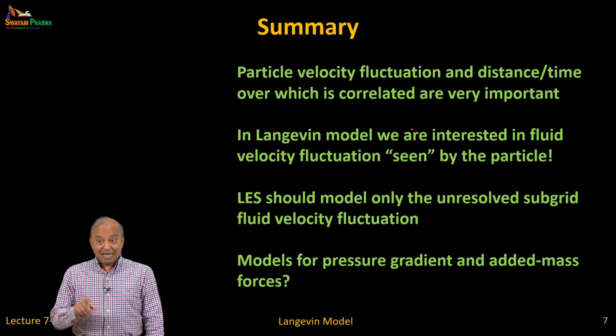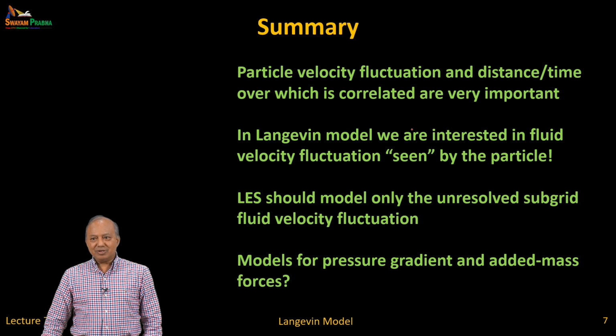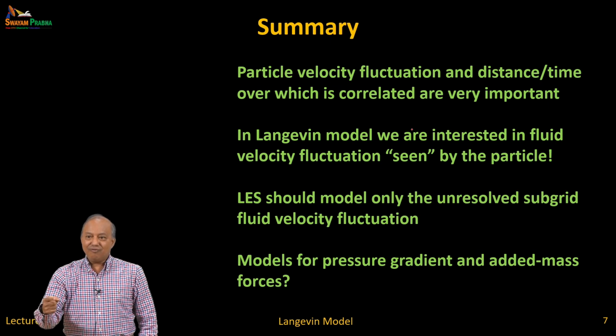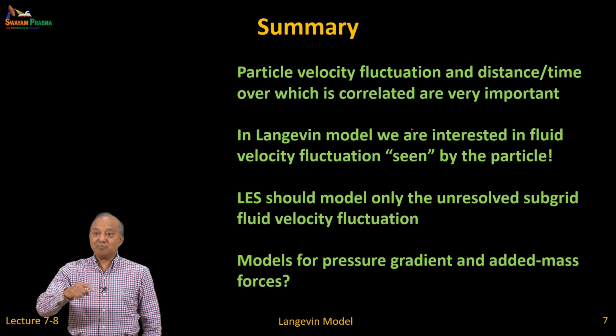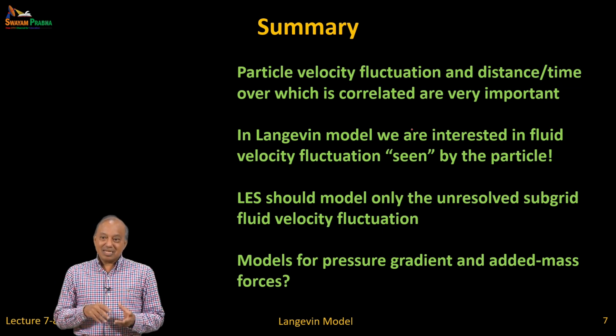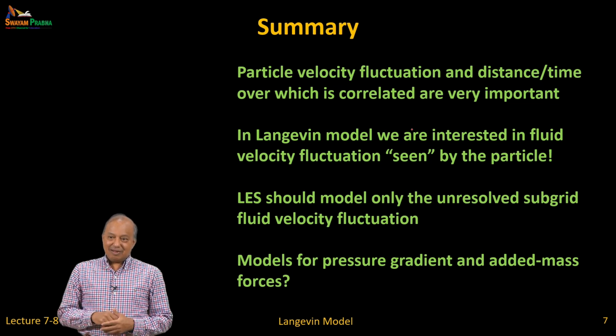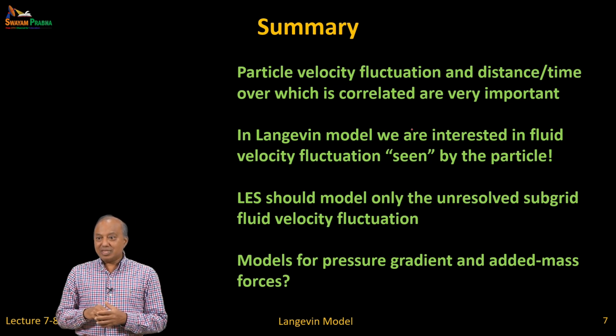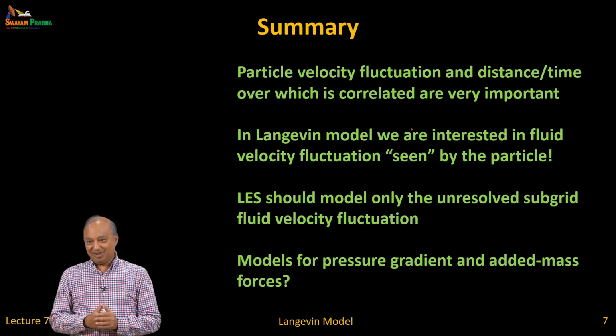So actually it's an excellent question that you're asking. When you do this, even though the RANS may be steady flow, the particles must be dynamically calculated, because this randomness will change from particle to particle. So RANS with the Langevin model will be more expensive, but you get the right behavior.